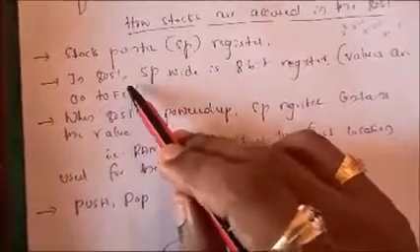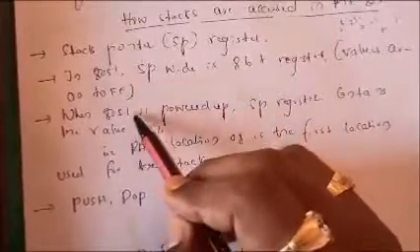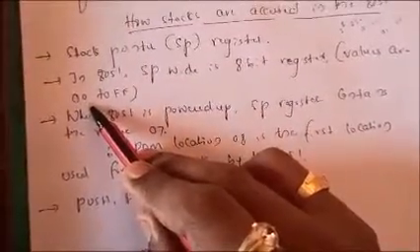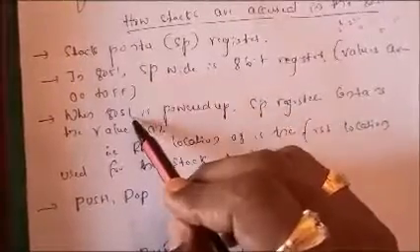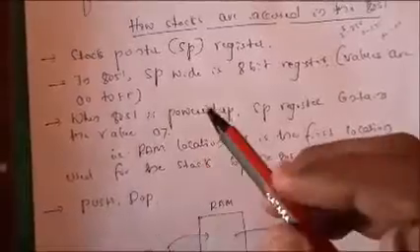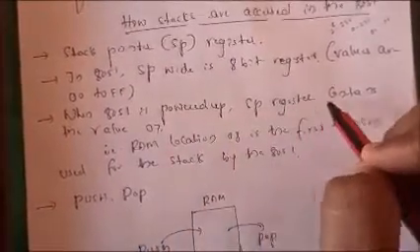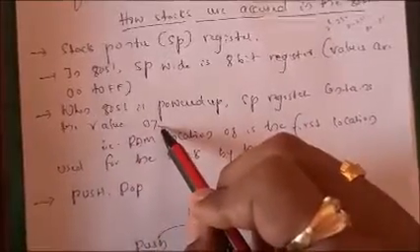So if anybody asks, sir, after FF what will happen? Again it will roll over. Rolling over is nothing but once you cross FF, it starts again from 00 itself. That means we call this a roll over from FF to 00. So again, as I already said, when you power up the 8051, the stack pointer is going to contain the value 07 only.